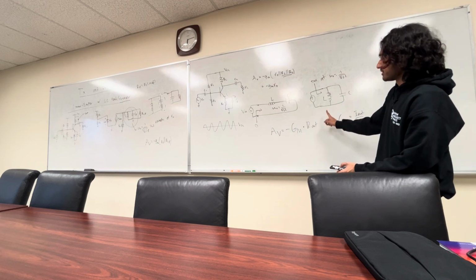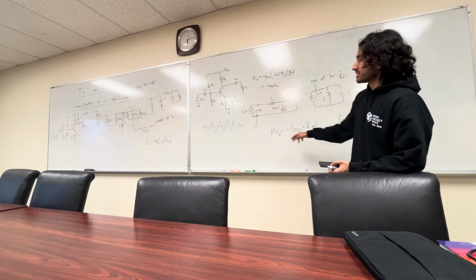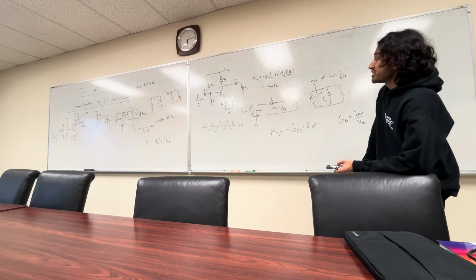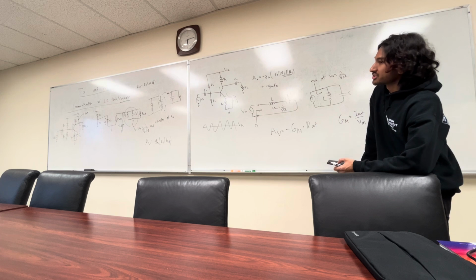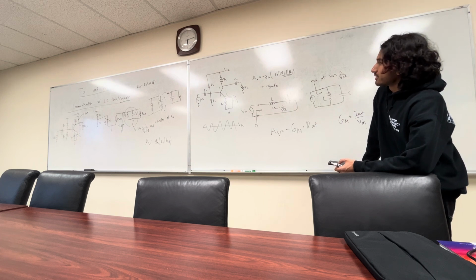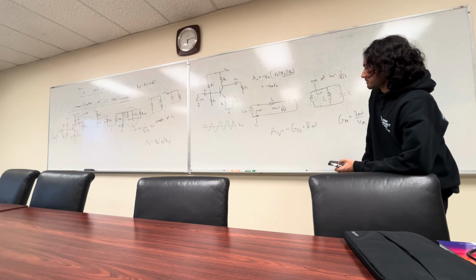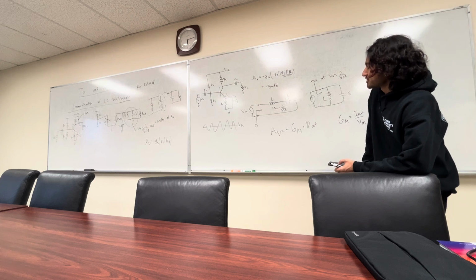So R out increases, so we can see our gain is going to increase from this proportionality here. Our GM also increases slightly because we have an inductor to bias. It's a bit weird to think about. You can go through all the math if you'd like, or I can find a derivation later and post it.